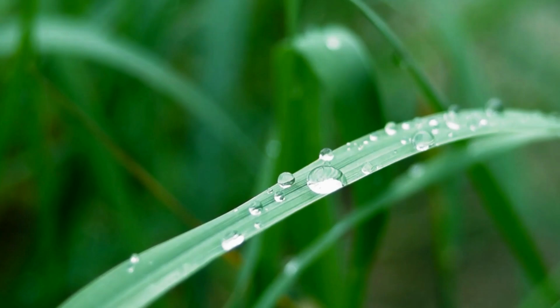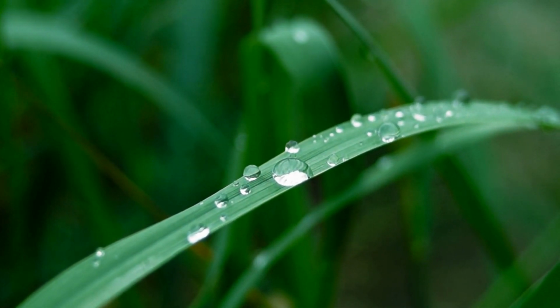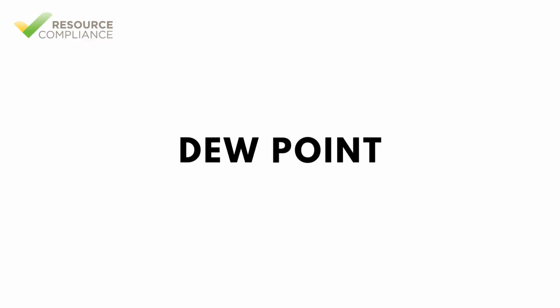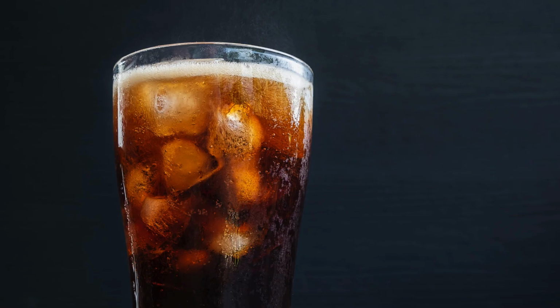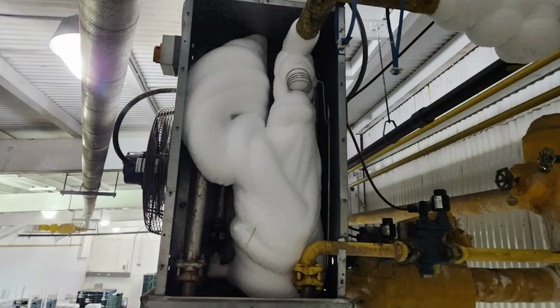Dew point is the temperature at which air must be cooled to reach 100% relative humidity. When air comes in contact with a surface that is below the dew point, water vapor in the air will condense on the cold surface. We've all experienced this when drinking an ice-cold beverage. This can be problematic for air cooling evaporators that operate below the freezing point of water.